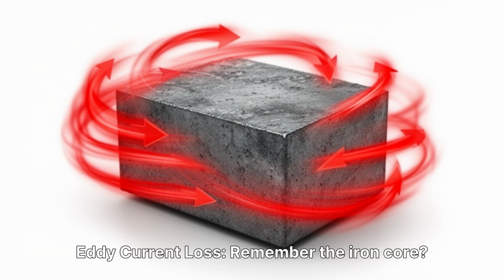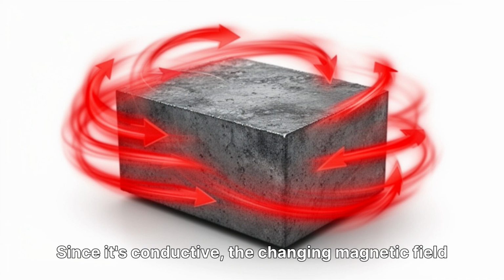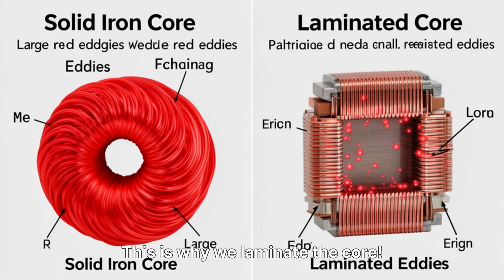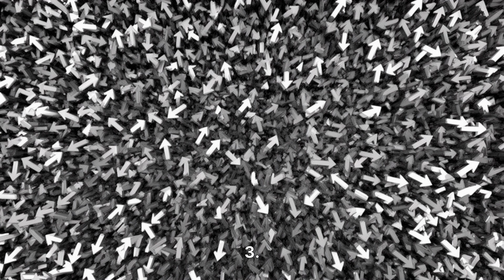2. Eddy current loss. Remember the iron core? Since it's conductive, the changing magnetic field induces small swirling currents inside the iron itself. These are called eddy currents. They generate useless heat. This is why we laminate the core. By slicing the core into thin sheets and insulating them from each other, we break the path for these currents, significantly reducing the loss.